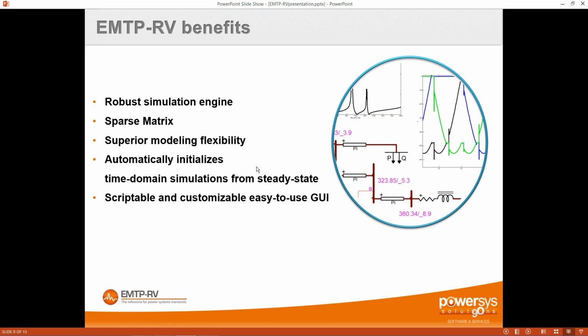So in EMTP, you set all the power constraints, you run the load flow, and then during the steady state solution, the power angle of each machine on the network is initialized. So the position at t equals 0 is found. Also, the voltage to apply on the field of the machine is calculated as well. So it makes it very easy to just start the simulation and everything is initialized. There is no initial transient.